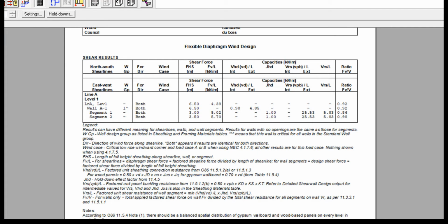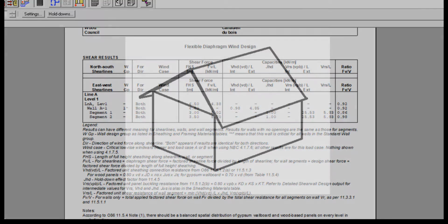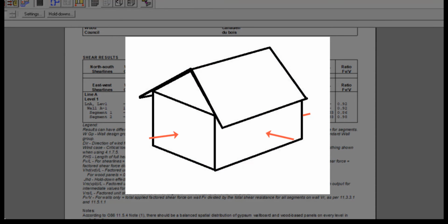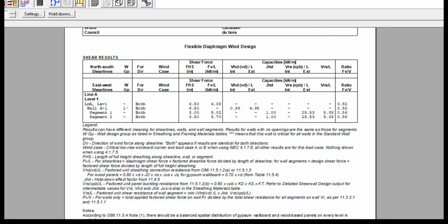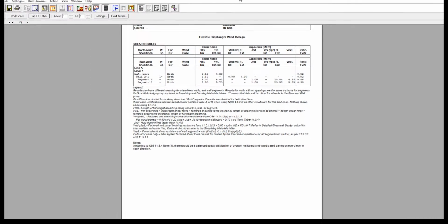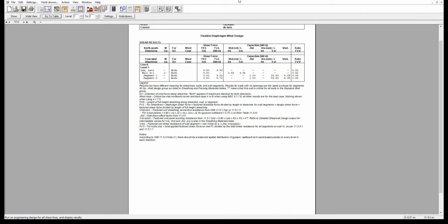When designing with shear walls, and when automatically generating loads, only horizontal wind loads are generated based on the walls, floors, and roof areas. In reality, vertical forces like wind uplift loads and dead load that resists overturning forces also exist, but these are not generated by the WoodWorks software, as the level of load is dependent on the orientation of the framing members. Since it is not currently possible to specify the orientation of the framing in shear walls, it is necessary to apply these loads manually, which I will demonstrate next.